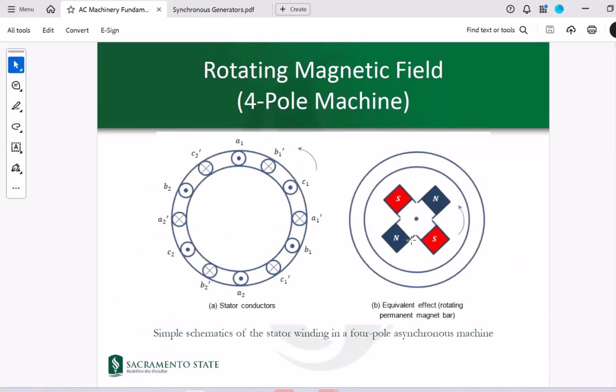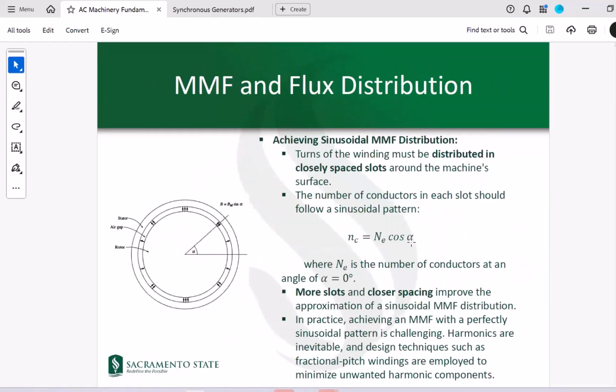In the design of electric machines, we want to design the field in a way that its distribution is sinusoidal. This means that if you're sitting in here and you rotate by the alpha angle around this stator, we want to see the minimum here, the maximum in here, zero here, then minimum here, and then zero again, based on a sinusoidal pattern, not any other form of pattern.